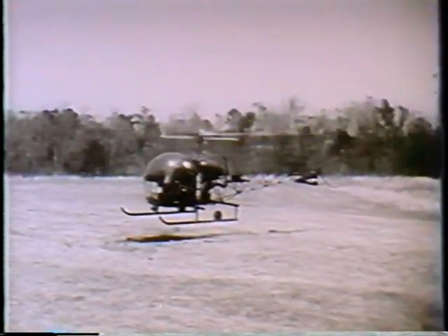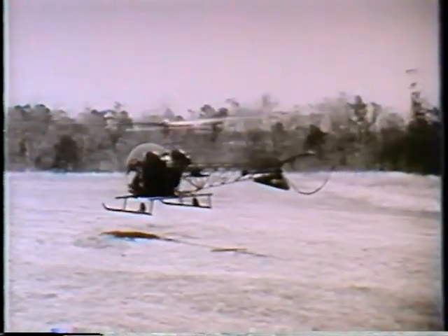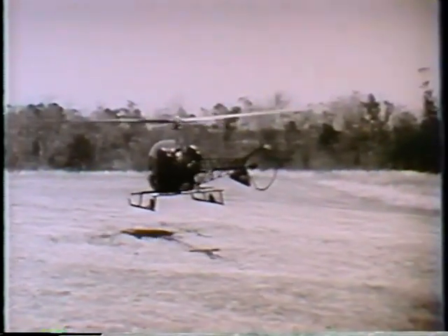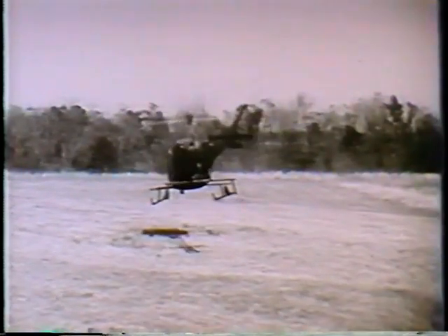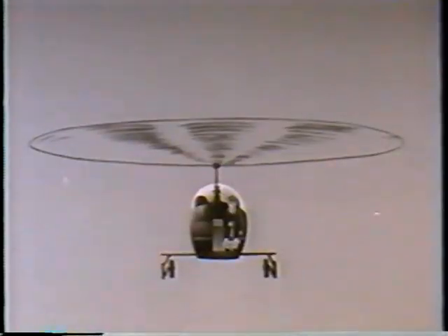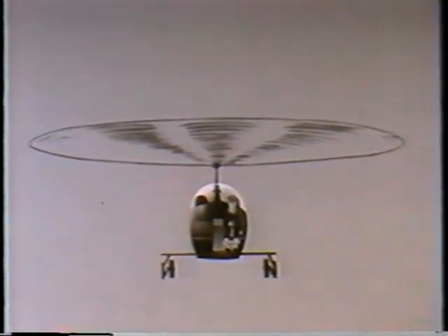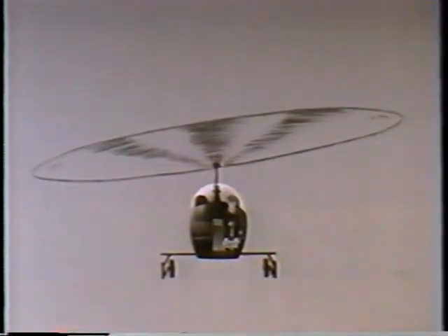No matter which mechanical means is used to permit the flapping action, the blades will follow the same path and produce the same result, an equalization of lift. Now, by the use of the cyclic control, the pilot can vary the amount of lift produced by the advancing and retreating blades, and can change the attitude of the rotor disc at will. By changing the attitude of the disc, he can maintain the desired attitude of the helicopter.